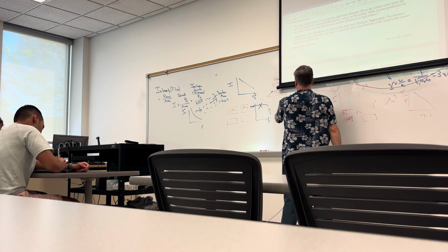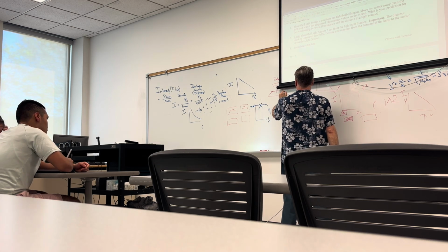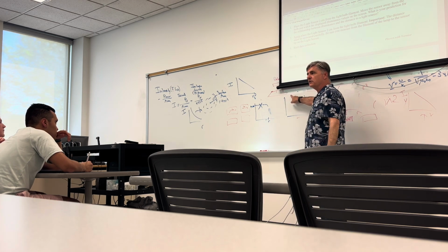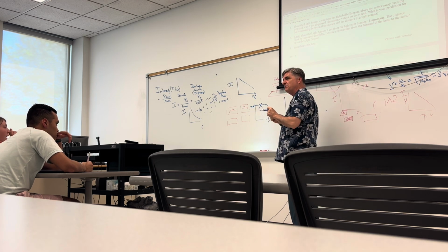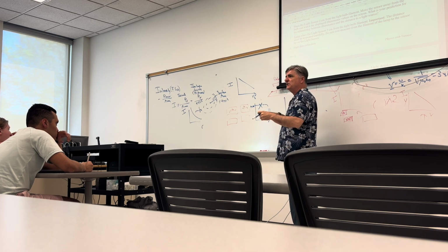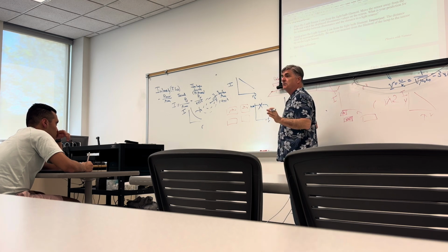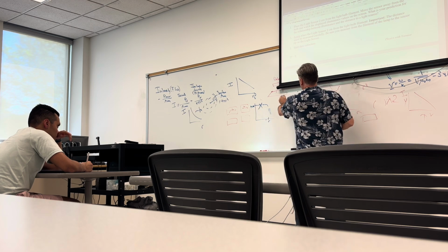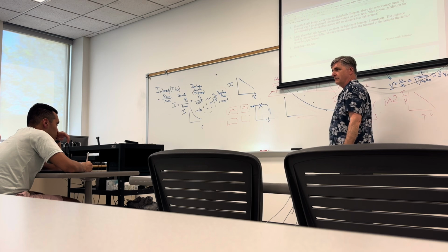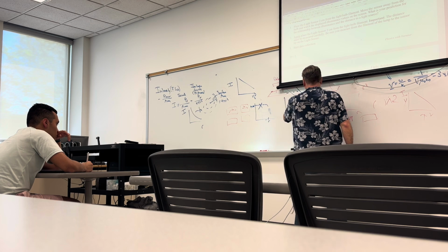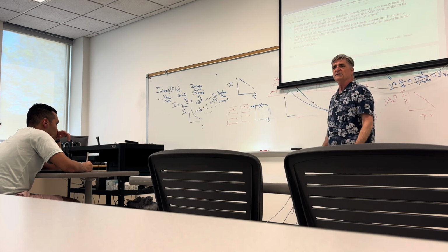So let's say your data points look like this. It's gonna try to average that guy in, but he's part of the plateau. What I'm telling you is don't collect that guy. Do a preliminary experiment to move that guy close enough once you've zeroed your lux meter to get rid of that. Now, if Tim doesn't want you to zero the lux meter, it's still okay. But still do that thing and don't collect the data point there because it's gonna try to average that into a curve, right? When we know this guy is flat topped, as we call it, when it's raised to the maximum of the sensor, we want a curve that's gonna fit the data better based upon that.